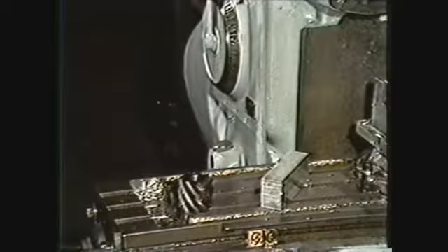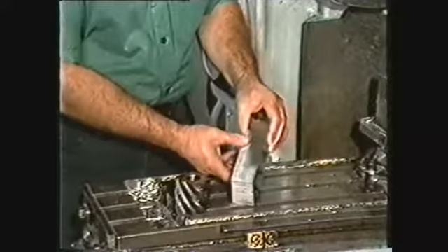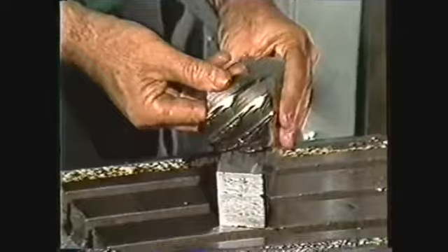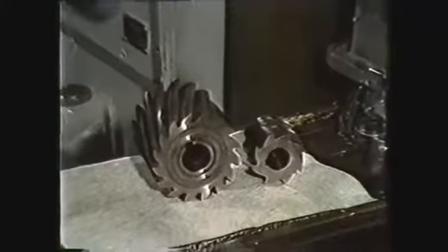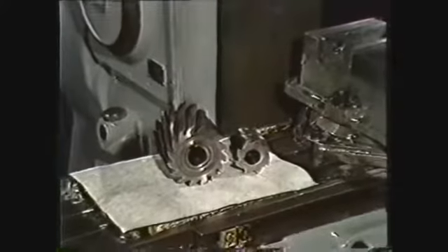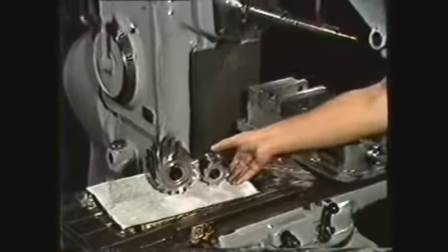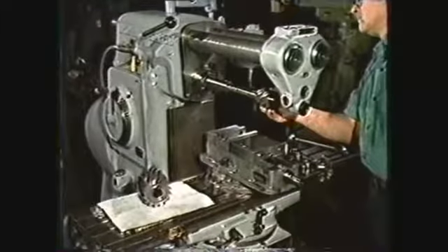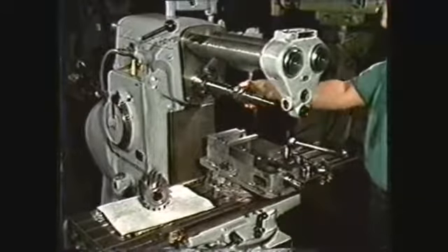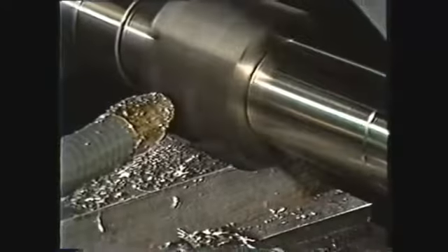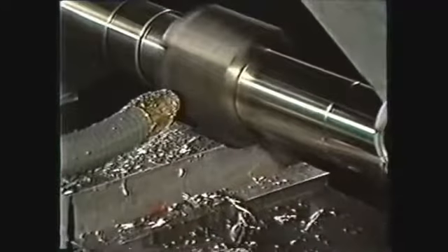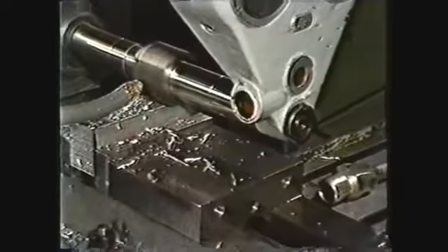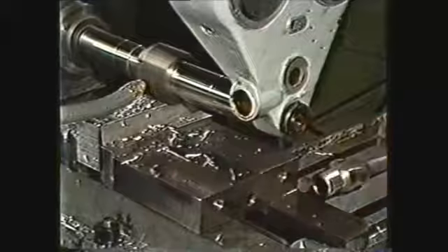When selecting a cutter for a plane milling operation, determine the width of the surface to be machined and choose a cutter that is wider than the surface. The next consideration is the diameter of the milling cutter. Select a cutter with as small a diameter as is practical, because the smaller diameter cutter uses less machining time, making it more efficient. When deciding on the diameter of the cutter to be used, you should take into consideration the amount of material to be removed and the clearance between the arbor support and the vise.